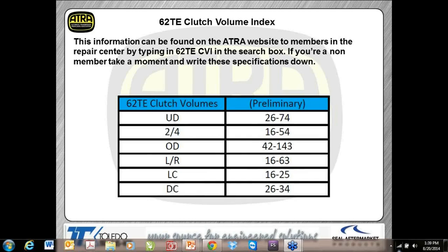Now here's the application chart. Obviously this unit does have a Sprag, which is really good for non-synchronous clutch apply and release. The thing that I've noticed too is when you talk about other transmissions that don't have Sprags in them, the ZF 6-speeds, you'll notice that unit doesn't have a Sprag, and it always seems to be a complaint of 2-1 downshift clunks. Now I know there's been plenty of updates to the computer to try to help prevent that. It doesn't seem to really get rid of the problem.